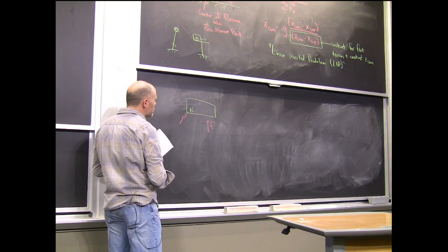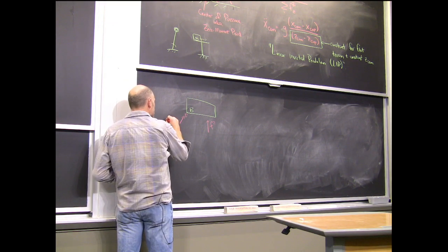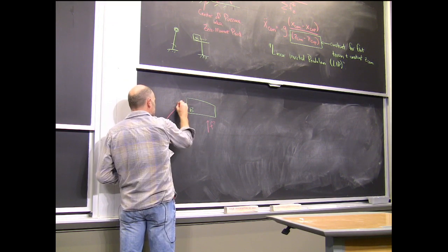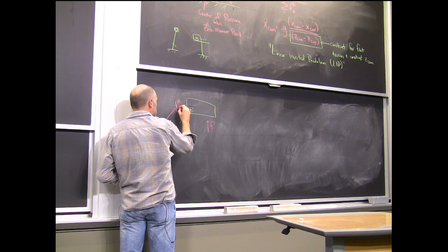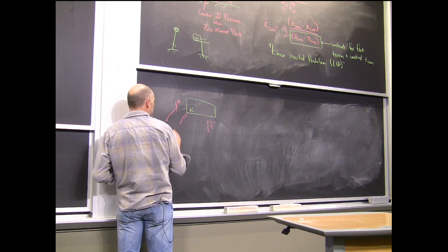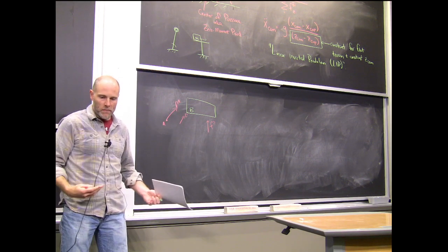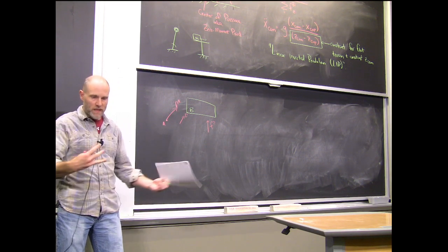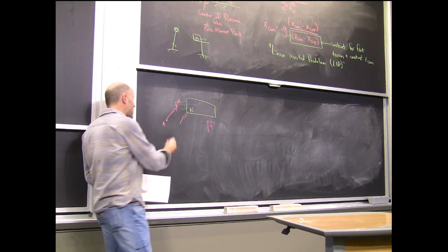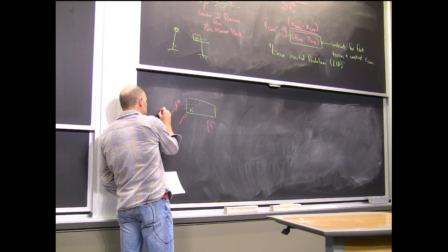I can always summarize all of the forces as a single force at any point, call it point A. I can summarize the total effect on a body from many forces as a single force plus moment.